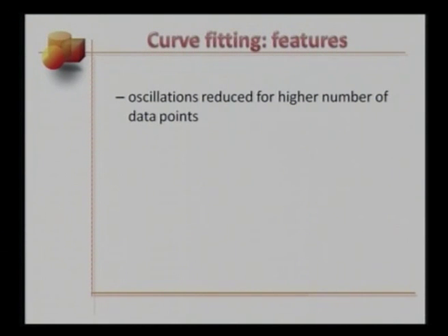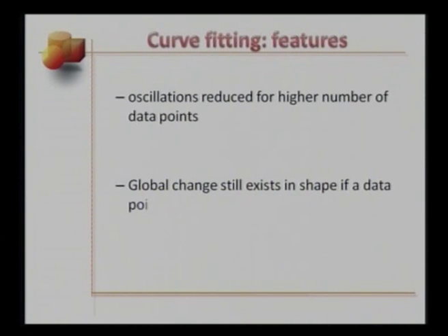Some features of curve fitting. Well, the oscillations get reduced for higher number of data points, which is expected since we're using low order or low degree curves to fit the given set of data points. But we still see global change in shape if any data point is moved. We still do not have local shape control on the curve.